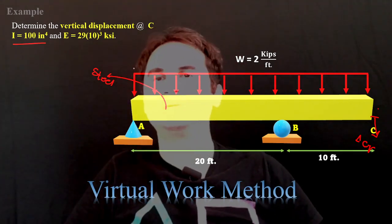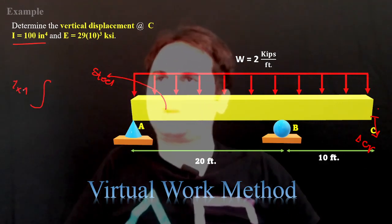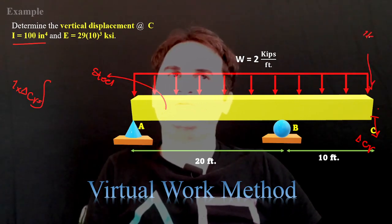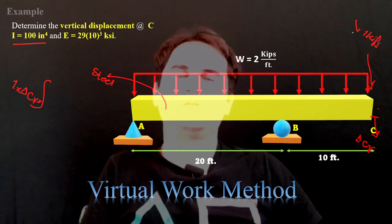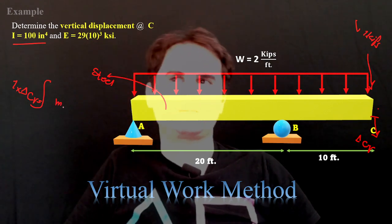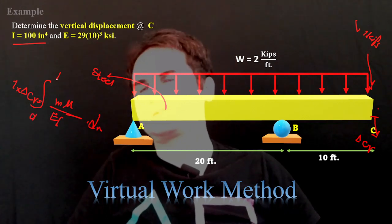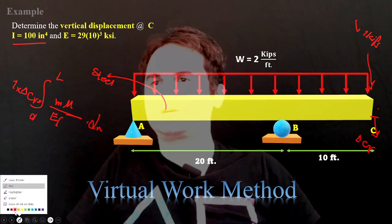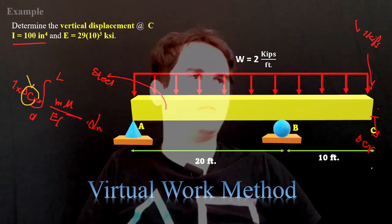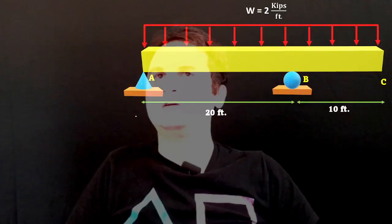In this kind of problem, by simply jotting down the equation, 1 times delta CV is equal to applying a 1 kip vertical virtual force, then we can create small m, capital M, over EI dx, and if we integrate it from 0 to L, it simply gives us what we are looking for, which is the vertical delta at point C. So we have to create the small m and capital M for our figure.